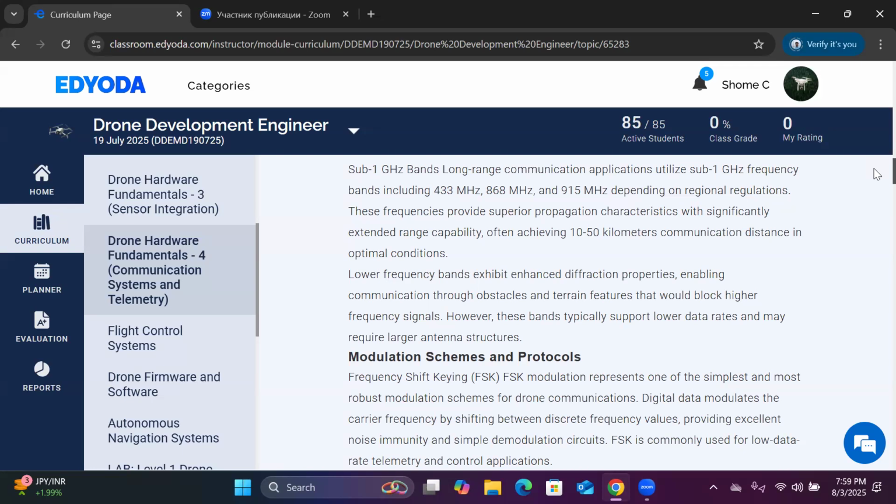But what I can tell you is what we have employed for the drone swarm: we have not used the 5.8 gigahertz module. We have used the 2.4 gigahertz module only. For our drone swarm for the defense, the requirement was to use 10 drones. A group of 10 drones will be performing the drone swarm activity because they want to do some kind of weapon check, some kind of bombing check, all these things in this drone swarm activity. That kind of activity needs to be checked by considering 2.4 gigahertz and sharing the bandwidth.